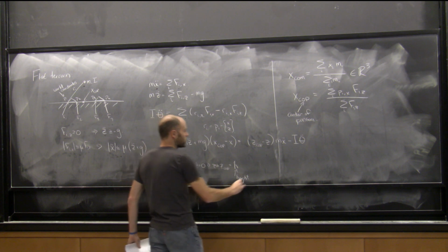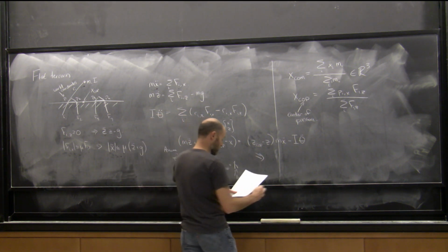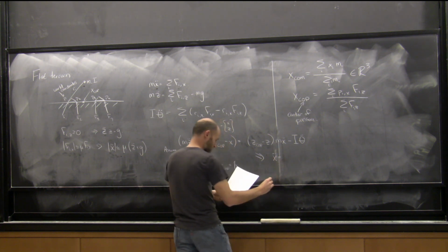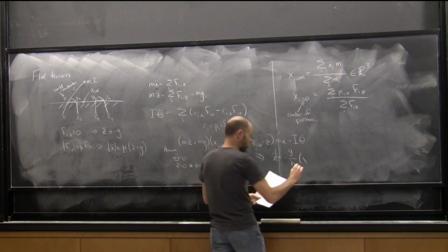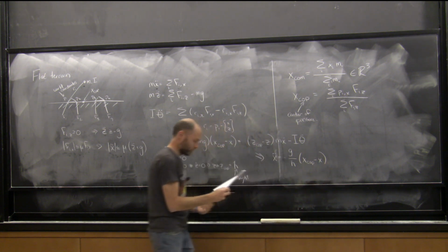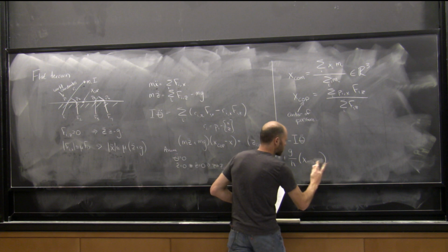So if I'm in this world of walking like this, then my height is just a constant. And this equation simplifies down to x double dot is just negative g over h times x COP minus x. Or if I want to flip that around, just to get the sign better, x minus x COP.